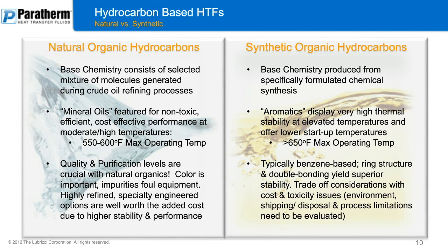So mineral oils are featured for their non-toxic, efficient, and cost-effective performance. And this is a key point here when we're talking about the selection process. Budget-minded and also capability-minded, they're very good at a range from moderate to high temperatures. So you're looking at a max operating temperature between 550 to 600 degrees Fahrenheit. So from there, you can see where we're already starting to, by classification, limit our selection process.